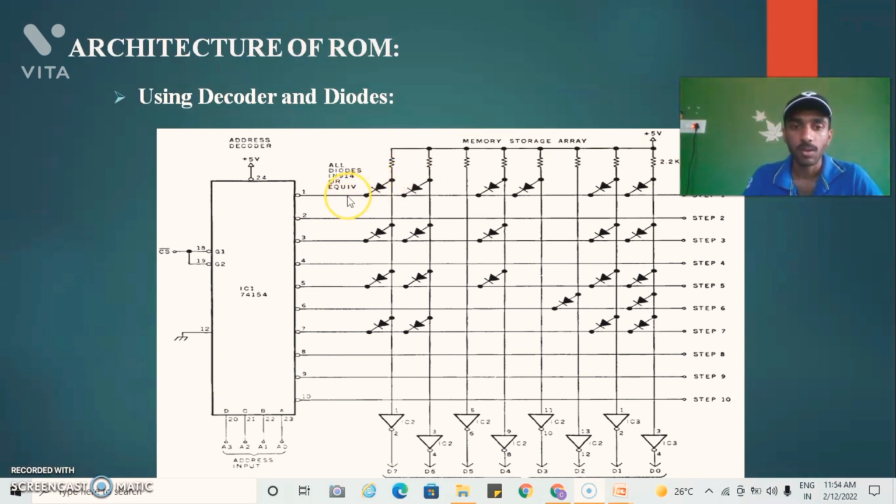Therefore the M0 word line is connected to the data line, so the data line contains the information present in the word line, that is logic 0. When logic 0 is sent to the input of the NOT gate, it reverses the logic and gives the output as logic 1.